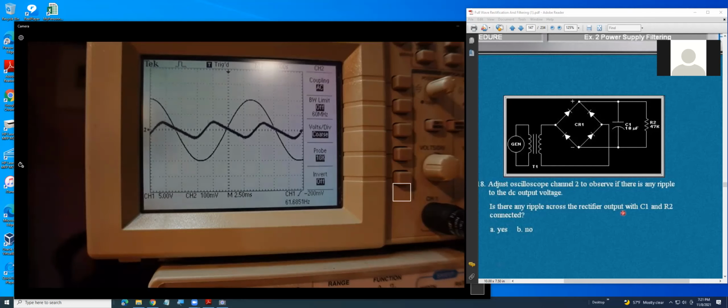Approximately how big or small is the ripple? Normally, when we design a circuit for a defense system, they ask for an output with 1 millivolt ripple maximum. On the DC, they want a straight line, with nothing on top, meaning no ripple on top of the DC voltage.